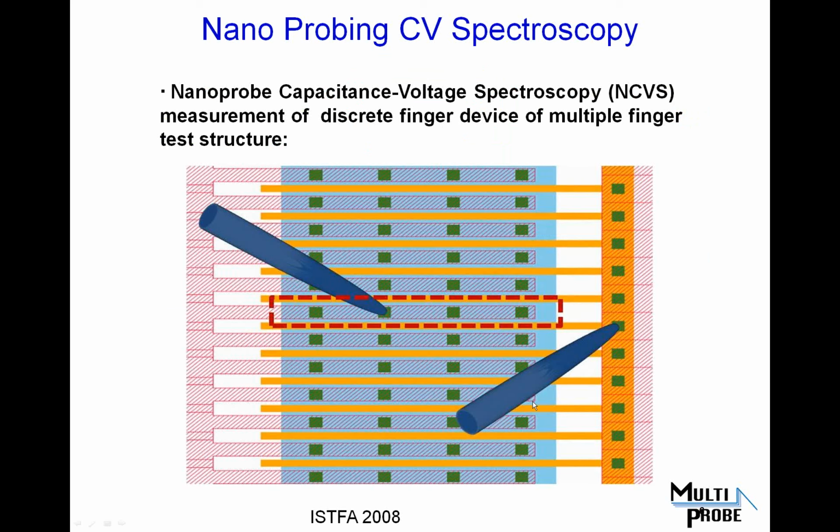The way this test structure is made is that you've got a source drain region here, which is like a single source in between two gates, and then the gate itself surrounds it, so it's almost like a ring structure. So nothing is happening at the source and drain above or below this part of the structure. So you only need two probes to be able to fully characterize. You're essentially characterizing half on one gate and half on another. Okay. Does that answer the question?